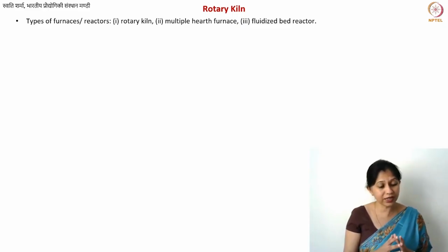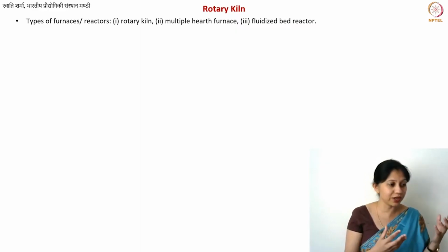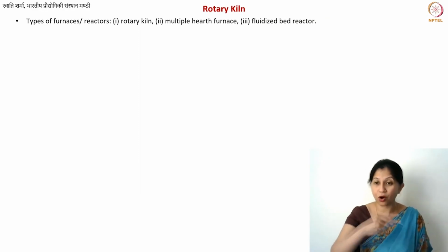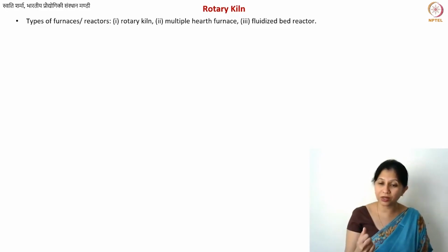Now when you use these kinds of massive furnaces, you may not be able to perform joule heating using coils, which you would do in a lab furnace. There you have a coil around your ceramic tube or quartz tube, and that is what provides the heat. But in the case of a several meters long furnace, you will rather use fuel. You will just use petroleum fuel, and using these hot gases, you will perform the heating.